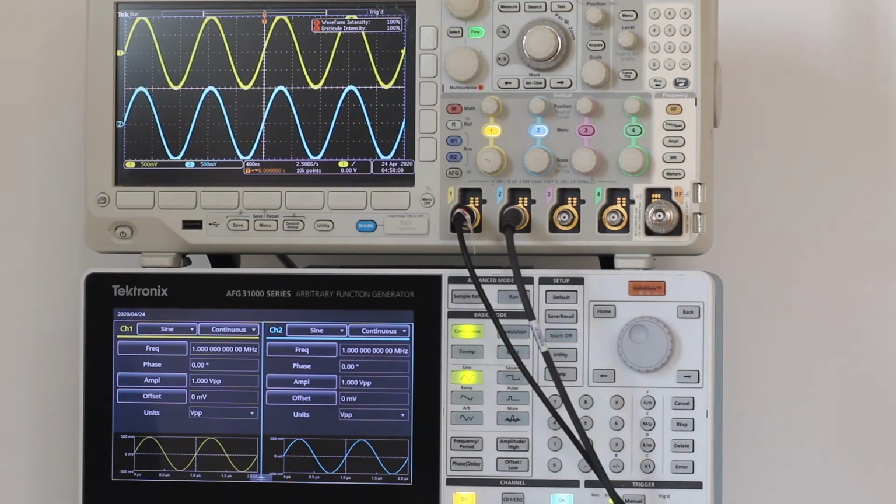The oscilloscope analyzes the relationships between two waveforms in the XY mode, in which their Lissajous figures are displayed. Two signals are required. One of them is connected to the channel 1 analog input. Using the old cathode ray tube terminology, after suitable amplification, the signal is fed to the vertical deflection plates, so that at any instant its amplitude is shown.